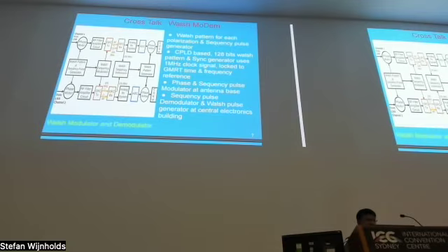Using that, Walsh patterns are generated for channel 1 and channel 2. Then it also generates a sequency pulse. The sequency pulse goes to the sequency modulator, and these Walsh patterns go to the channel 1 and channel 2 phase modulators to modulate the incoming channel signals. Once it is modulated, the signal goes to RF filters and amplifier circuits, then the other parts of the GMRT chain: OFC transmitter, receiver, then analog.